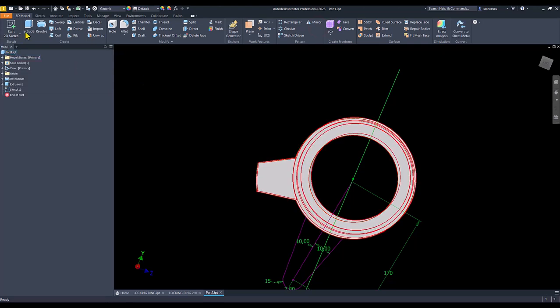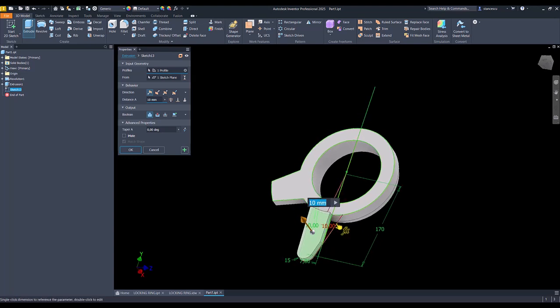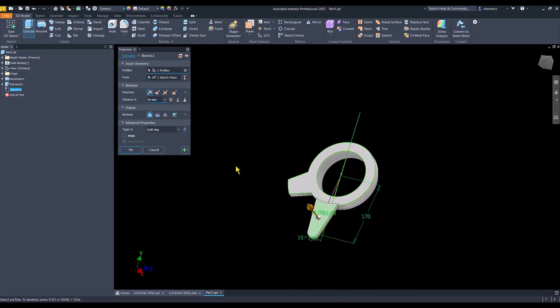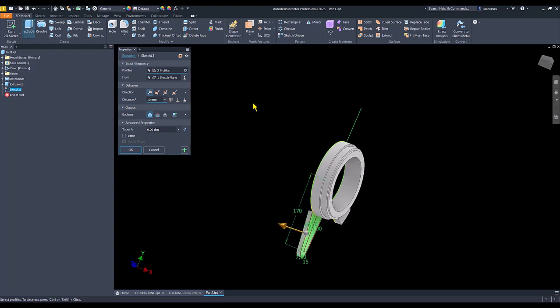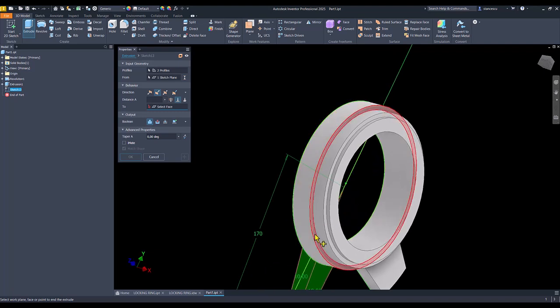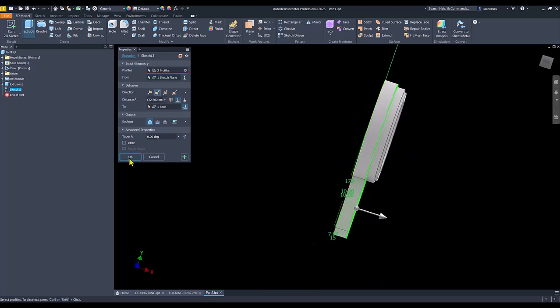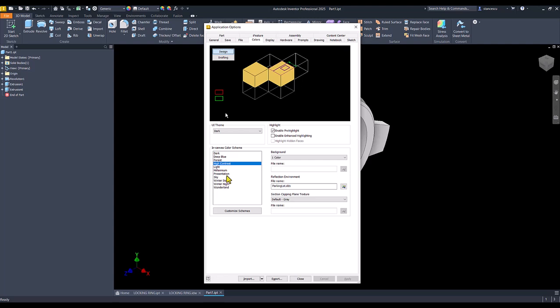Finish sketch, extrude, we have a separation because of this axis, and the other direction to this face. Okay, I go back to normal background, Alt F, I in sequence to obtain this application options. You know this from my previous tutorial.